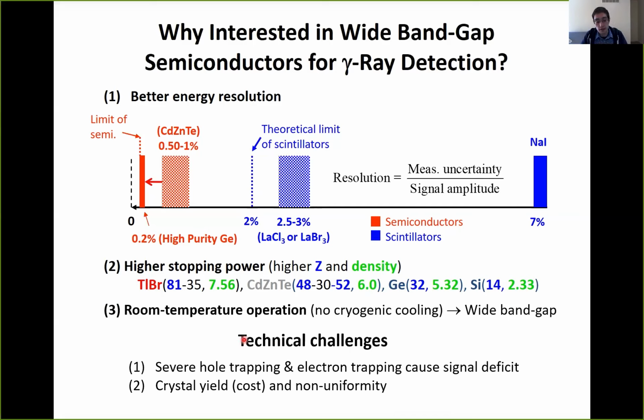So in regular semiconductors, when a gamma ray deposits some energy and an electron is ejected, the vacancy is left. If there is a bias across the detector, because there is some voltage across, the electron and the hole will drift towards the respective electrode. So right here, this is the anode, and the electron will drift towards the anode because it's positively charged, and the hole will drift towards the cathode because it is negatively charged. But in CdZnTe, that is not really true. Holes do not really move. We actually assume that the hole doesn't move.